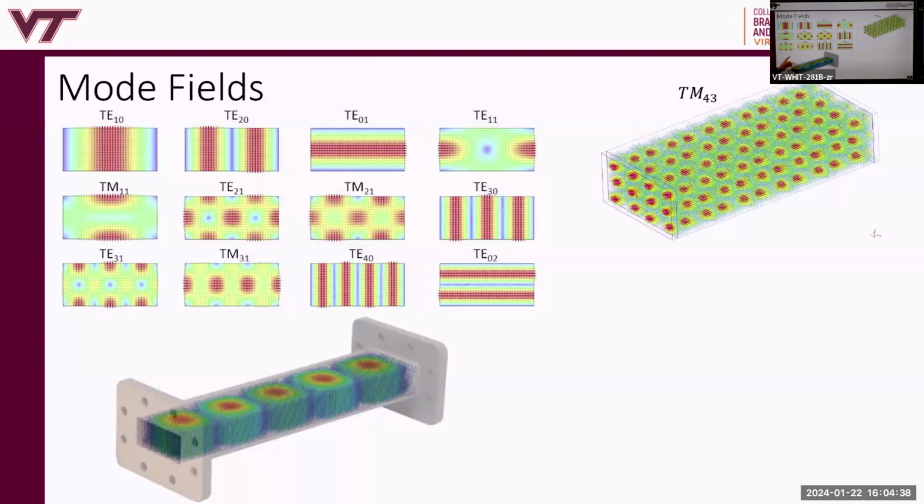I take a cross-section, I get this modal field distribution, this vector field in the cross-section of the waveguide. Now, this vector field does have z-dependence, e to the minus j beta z z. And therefore, each of these vectors is going to vary with z, but they all vary together, right? So the whole vector field in the cross-section of the waveguide will vary periodically.